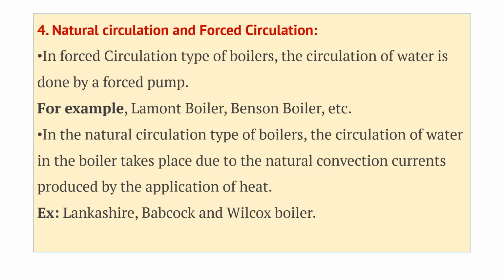If the water gets heated, automatically it will become less dense. According to the principle, less dense water molecules will come to the upper section and high density water molecules will come to the lower section. Once the high density water comes to the lower section, immediately it contacts the heating surface and its density becomes less. So it keeps moving continuously until the entire water is boiled.